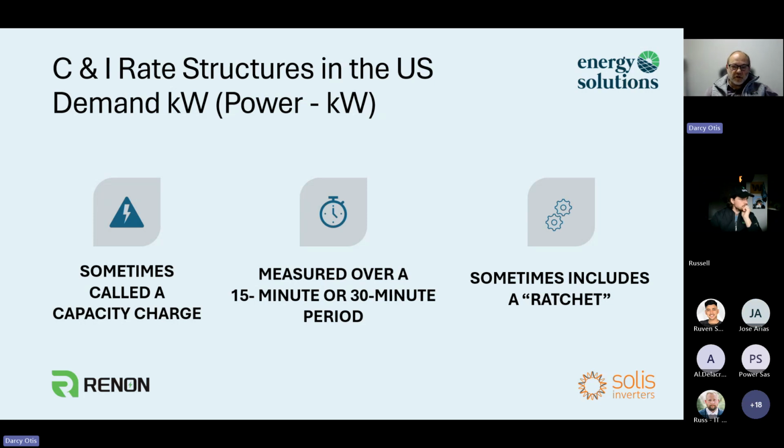It's usually measured in a 15-minute or 30-minute interval. So it's the maximum power consumed within an interval. And oftentimes it's multiplied by some sort of factor or a dollar figure per kilowatt. That could be a daily charge. Hey, it's so much per your maximum kilowatt a day. That could be some other time period, a monthly or within a billing period. Or it could be a scenario that's sometimes called a ratchet.